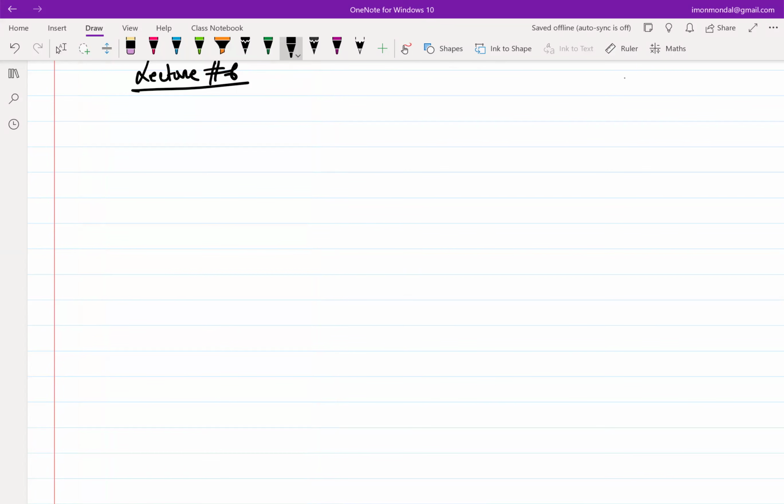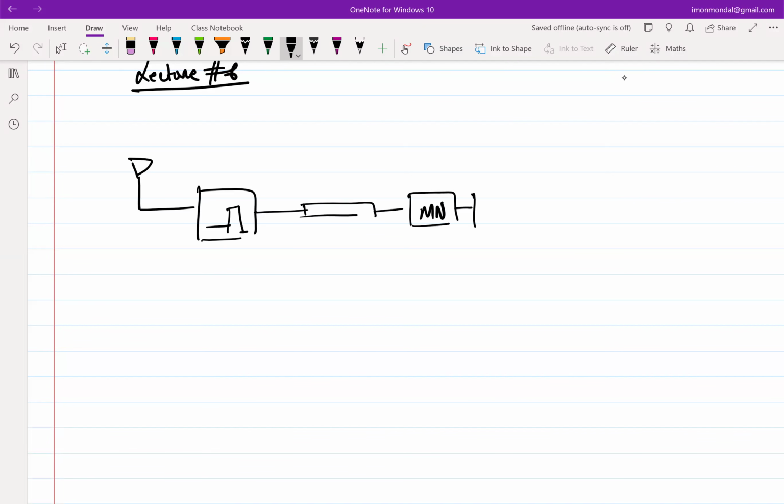So we rounded off the RF chain in the previous lecture. The only part that we didn't touch upon at all is how you generate clocks. If I only think about the receiver, you have an antenna, a SAW filter, a transmission line, some sort of matching network, then an LNA, maybe another filter somewhere, and ultimately you come to a mixer.